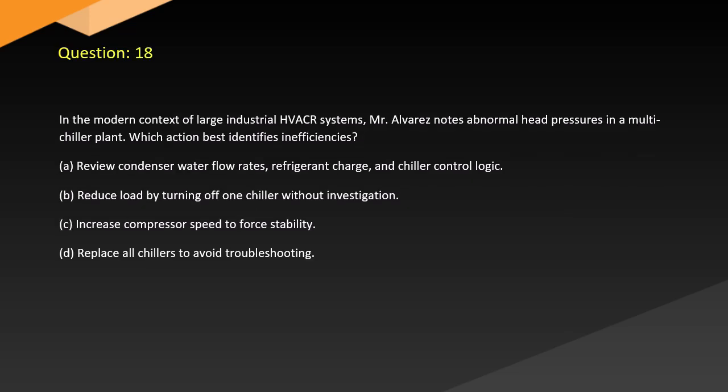Question 18. In a modern context of large industrial HVACR systems, Istaa Alvarez notes abnormal head pressures in a multi-chiller plant. Which action best identifies inefficiencies? A. Review condenser water flow rates, refrigerant charge, and chiller control logic. B. Reduce load by turning off one chiller without investigation. C. Increase compressor speed to force stability. D. Replace all chillers to avoid troubleshooting.